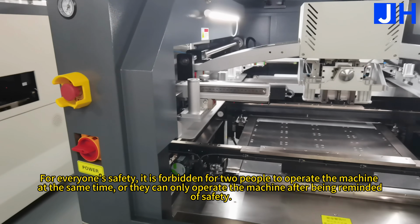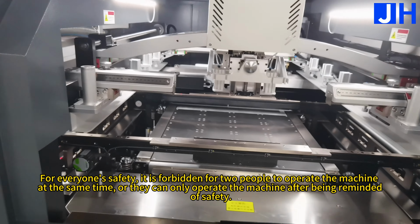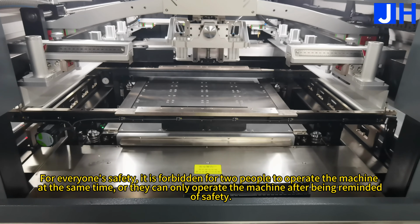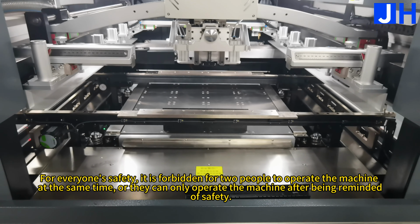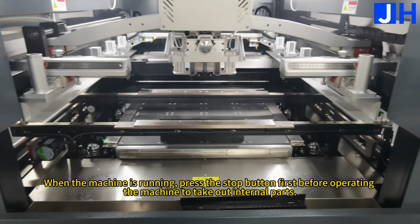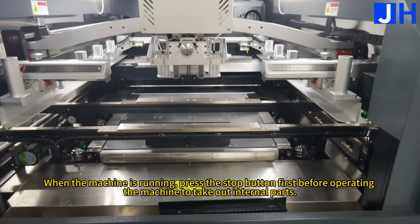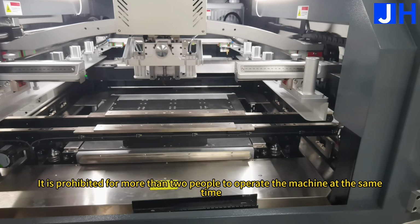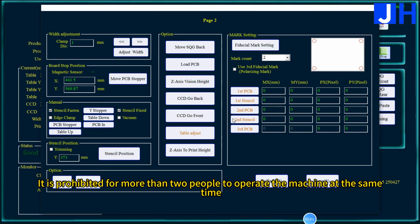For everyone's safety, it is forbidden for 2 people to operate the machine at the same time, and you can only operate the machine after being reminded of safety. When the machine is running, press the stop button first before operating the machine to take out internal parts. It is prohibited for more than 2 people to operate the machine at the same time.